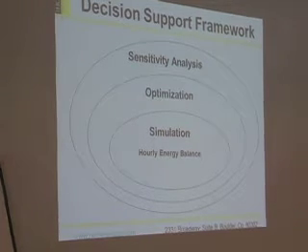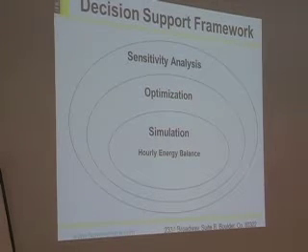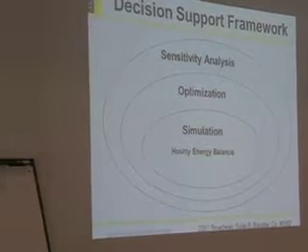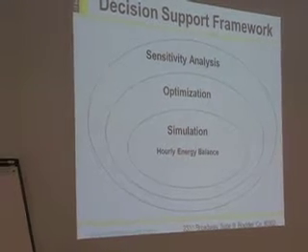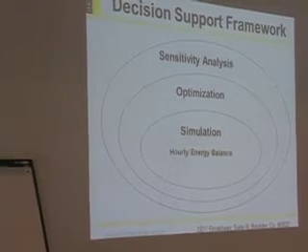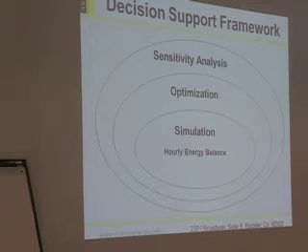At the innermost layer, we're meeting the load in every hour. So you have resources. Are they enough to meet the load? What is your load? Do you need to turn on a diesel? Do you need to charge or discharge a battery? And it does that time step by time step through a whole year. It's typically an hour, but it can be as short as a minute. I've got some examples of some analysis that we did in 1 minute time steps, which is, of course, slower. So that's at the hourly level. It does that for an entire year, and that tells you how one system operates for 1 year. And from that, you can extrapolate over its lifetime. But that's how one system operates. So that's a simulation tool.